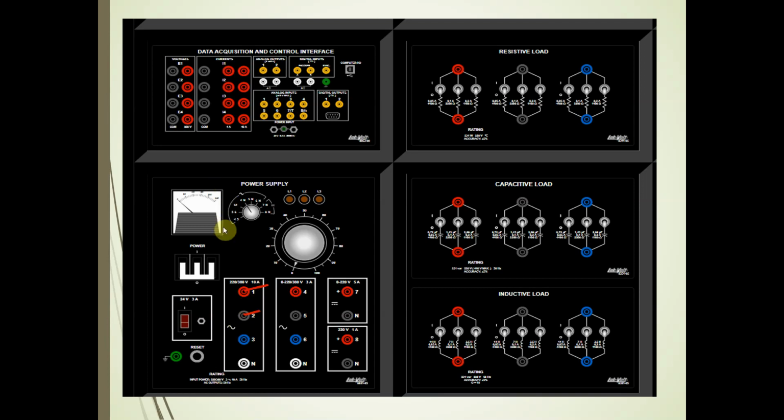Notice that I am following the sequence: the voltages, let's say E1-2, E2-3, and E3-1. Notice that I am following a sequence 1, 2, 3, because I am using the ABC phase sequence. This source is for ABC phase sequence. Suppose I don't want a source that is exactly equal to 380 or 220. Let's say my load requires 275 volts. So how am I going to do that?